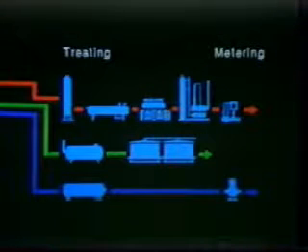For this reason, if a three-phase separator, free water knockout, or treater do not remove the oil from the water to an environmentally safe level, a coalescer or skim tank may be needed to segregate and recover the small volumes of oil still remaining in the water. The water is then usually metered before disposal.